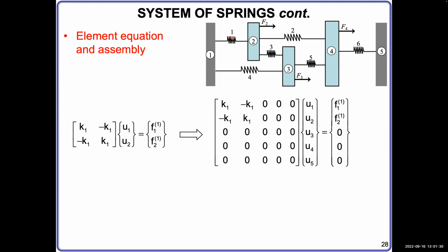What is a node? What is an element? What is the external force? What is the internal force? What is the displacement? What is Hooke's law? What is the relationship between internal force and external force during force equilibrium? Those important key concepts you should be very, very familiar with. Now, to solve this system, we constructed the equation set for individual springs one by one, and then we assembled all those individual equation sets together into a bigger one.